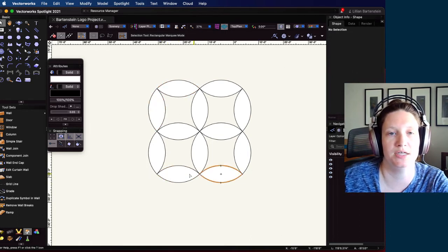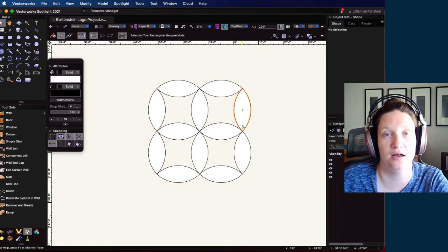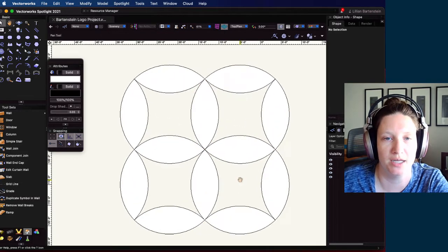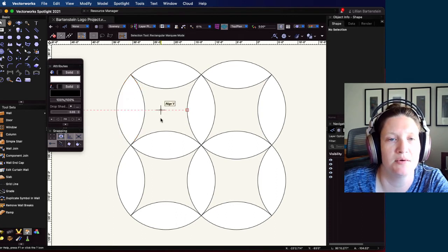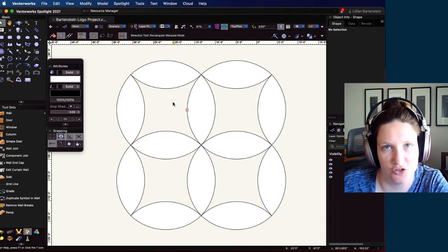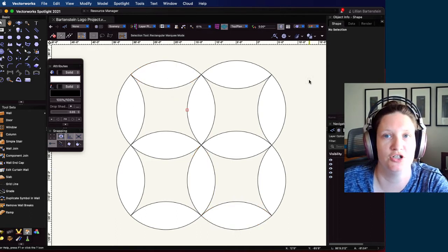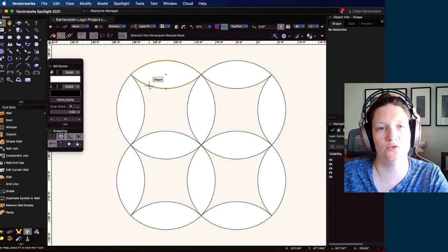We have these interior shapes that we're going to create an actual vector shape out of, right? You can see, right, when you zoom in on Vectorworks that some of them are white in the middle and some of them are kind of gray, and that's just like you're seeing the Vectorworks background behind. So we do want all of them to be shapes because they're all going to end up being colors in our final product. So in order to do that, we're going to use a tool called Combine into Surface.